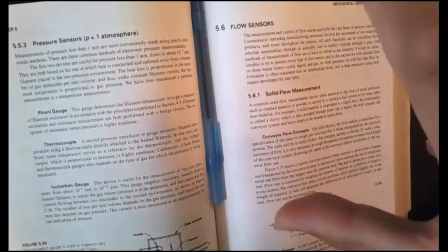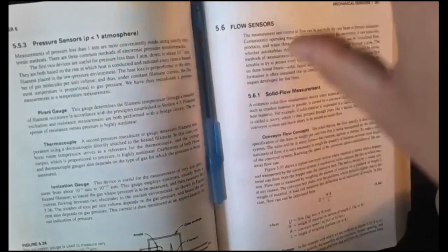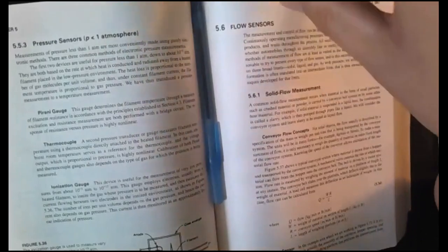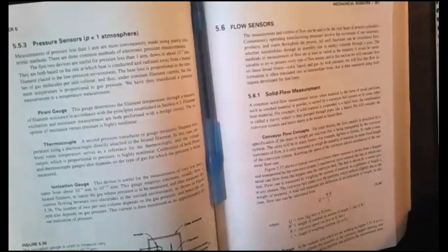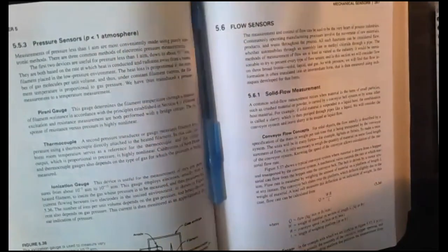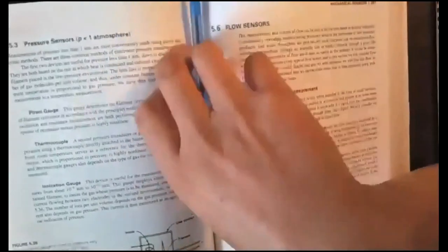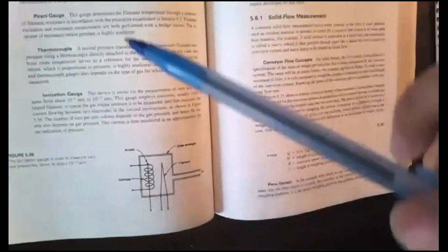So when you repair your AC, before you charge it, you have to use the vacuum pump to completely draw the moisture and the air out of your air conditioning unit before you charge them with freons. So how do you measure the vacuum?